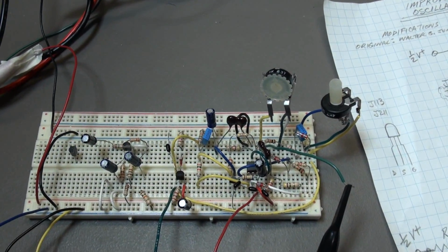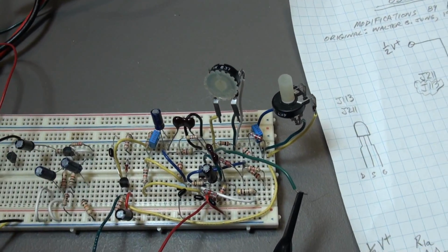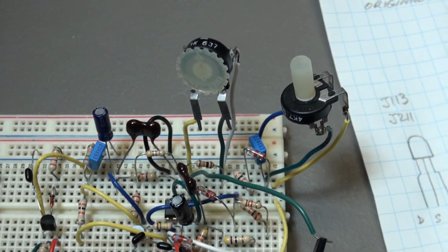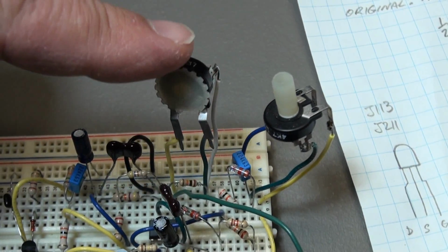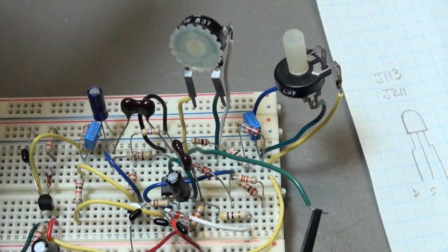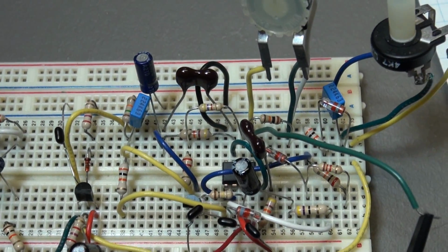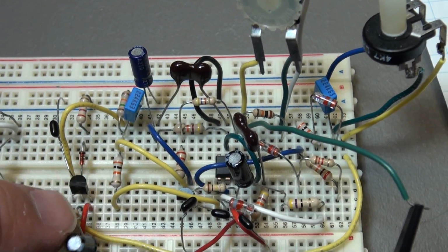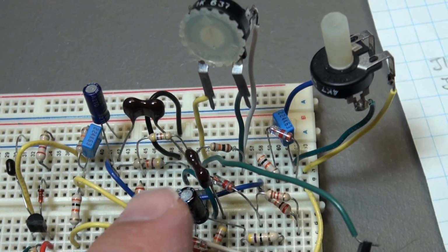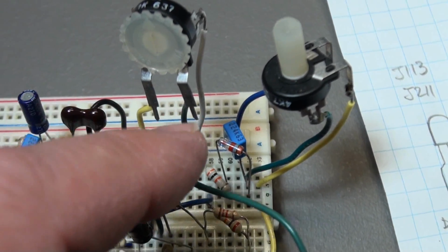So this is the circuit on the breadboard, this portion. This is something else. Let's just zoom in on that. So the two potentiometers, the distortion reduction adjustment pot is there, the amplitude adjustment pot is there, and the rest are, there's the voltage reference 1/2 V plus, the JFET is buried in there, the TLV2772 is in there too.